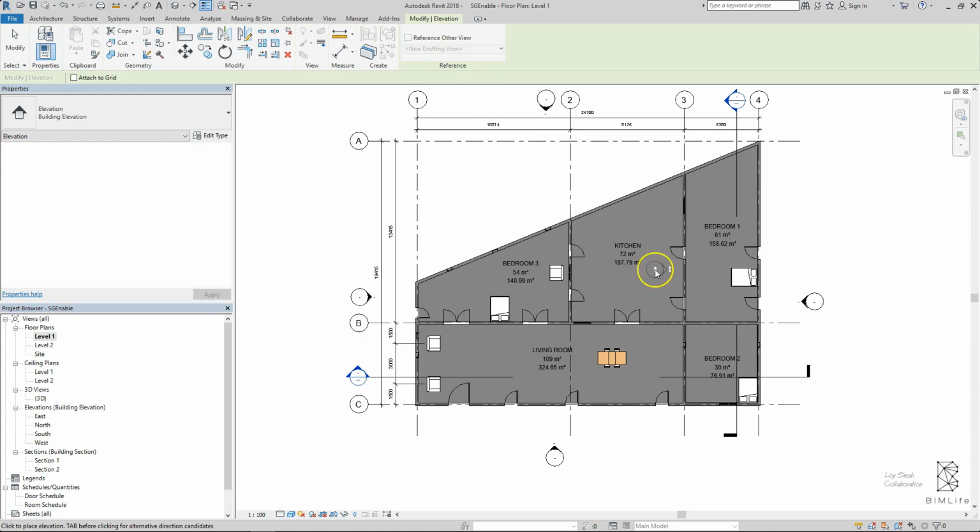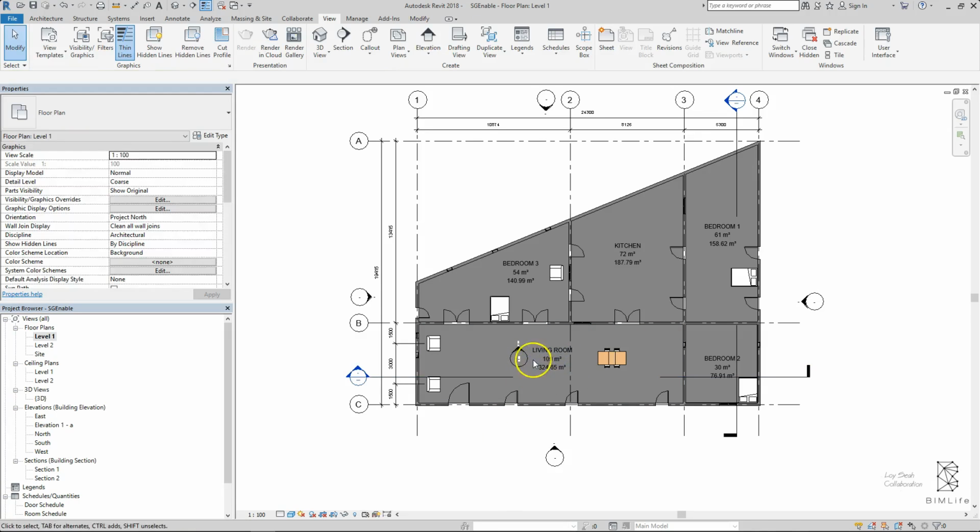When you move your mouse into the middle of the rooms in a project, you will see that Revit always tries to find the closest wall. Simply place your elevation down by doing a left click. Escape twice once you have finished creating an elevation. You will notice Revit only creates an elevation in a particular direction.